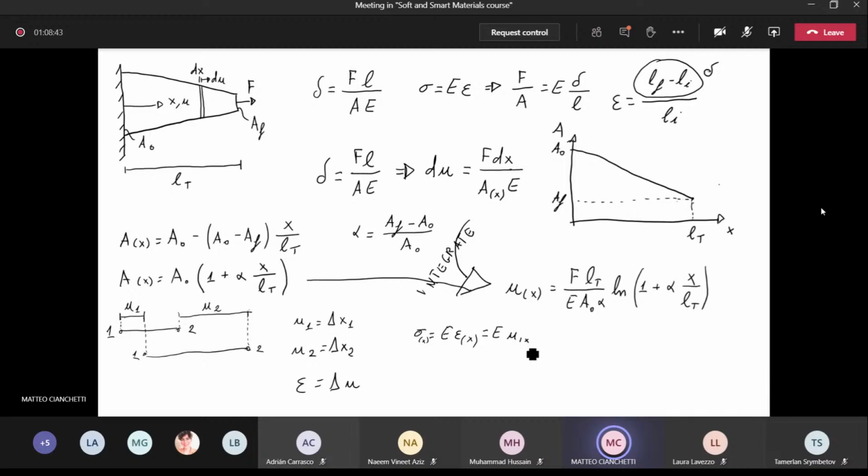Now, this is a very peculiar notation that is often used when we deal with finite element analysis. This is a sort of comma, actually. I said one, but this is a sort of comma. When you see this subscript u, comma, x, this means the first derivative of u with respect to x.